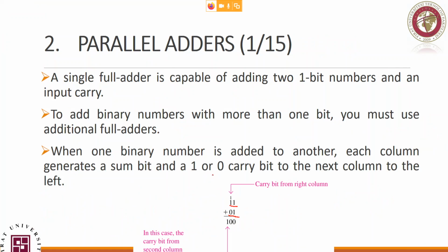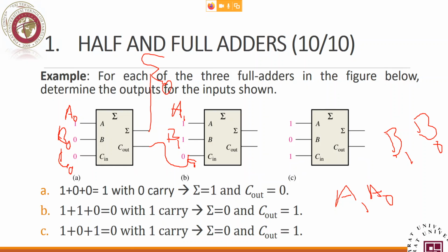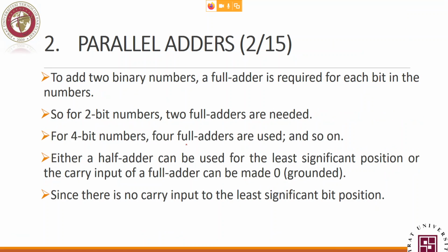This is the cascading process. This is what I refer to by cascading process. That accommodates for 2 bits. If you link these two together, cascade them, you will get an adder that helps you in summing 2 bits at a time, not just 1. That will be sum 0, sum 1. So what we will be having here, a summer, or an adder for A0, B0, A1, B1. All right. More than that, you need to cascade more.